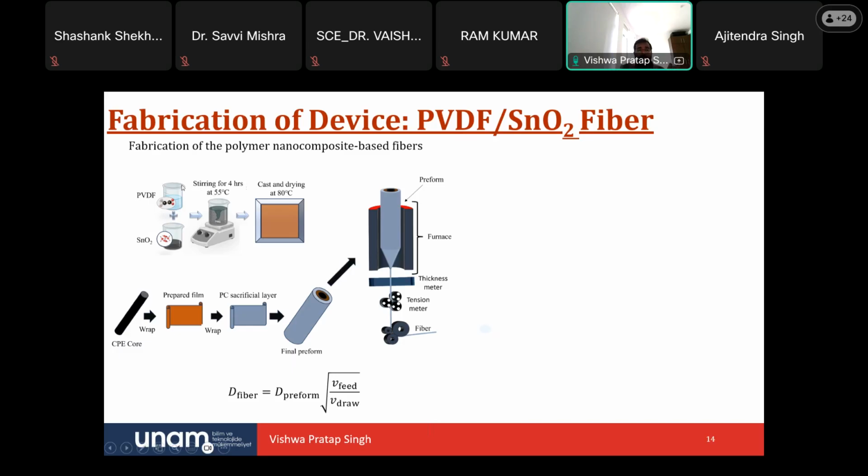So we have this polymer, PVDF. We use DMF, which is a solvent that dissolves the PVDF. So we dissolve the PVDF in that solvent and stir it for, let's say, 1 hour. Simultaneously, you put in SnO2 or any reinforcement, like any filler, to make a composite.